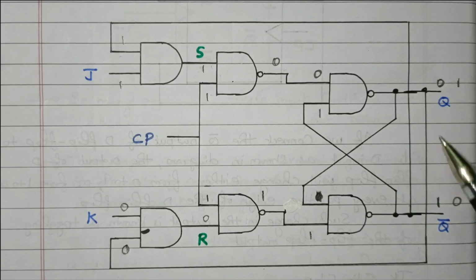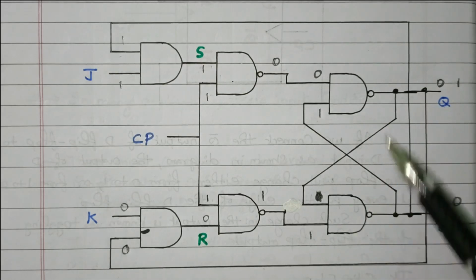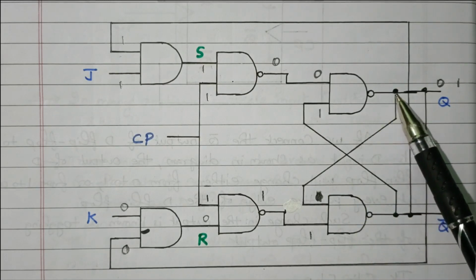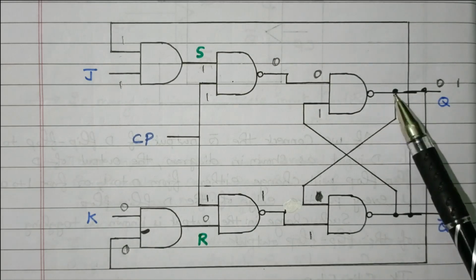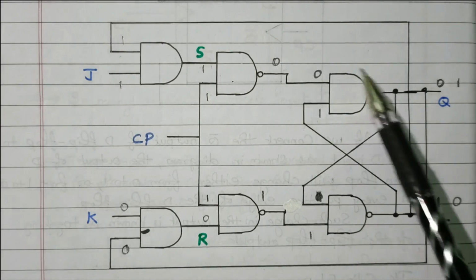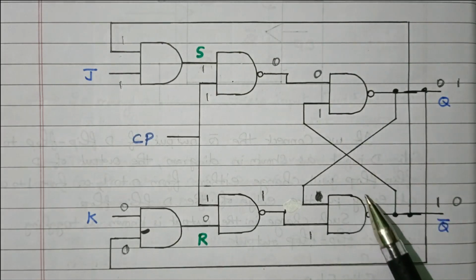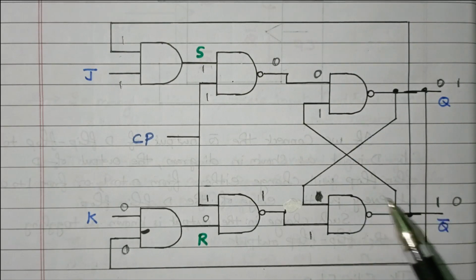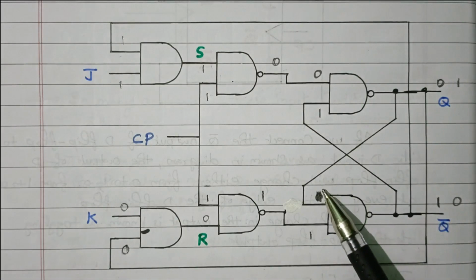Right? You have to follow from top to bottom. So both are interconnected. We don't know how it will execute, but we have to follow a certain procedure. You have to follow the top NAND gate first. From the change of output, that output is applied to the bottom NAND gate. For some 4 combinations we have to follow the top, and for another 4 combinations we have to follow the bottom. First we find the bottom output, and that output will be applied to the top NAND gate. So from the truth table we can decide.